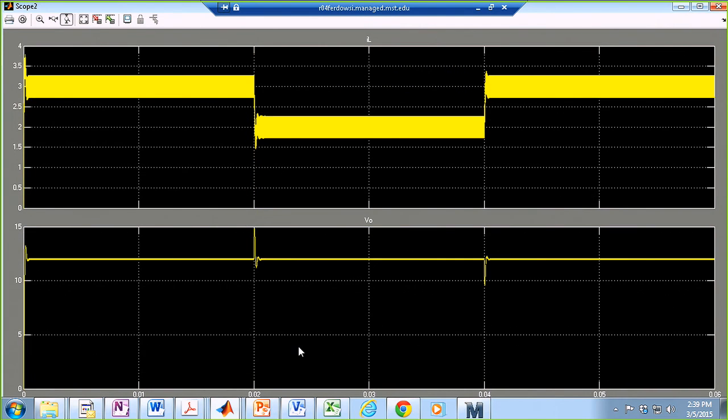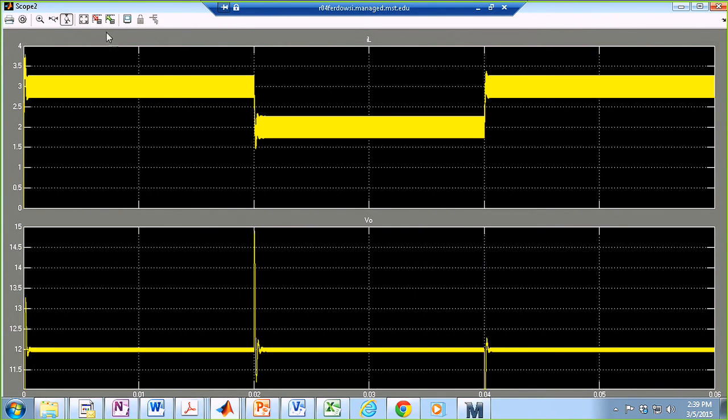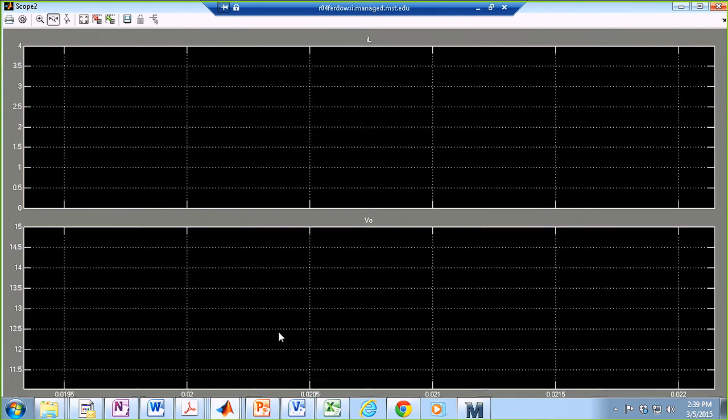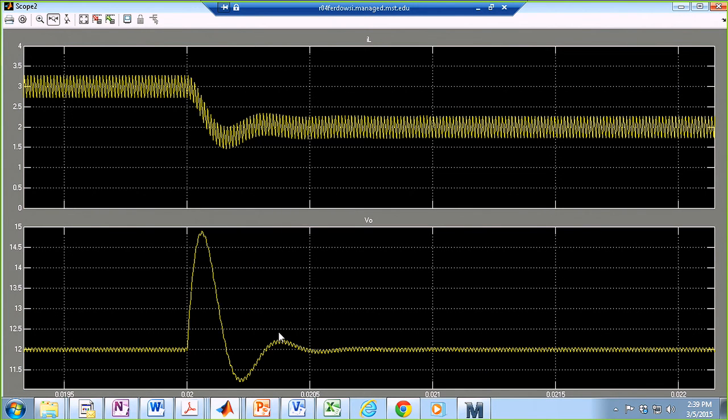All right. Technically, if our converter is ideal, we shouldn't see any changes in the output voltage, because the output voltage under steady state conditions is independent of the value of the load. But unfortunately, you see a behavior like this, for instance. So my output voltage before was 12. After the transition is over, it again goes back to 12, because under steady state conditions, load should not determine your output voltage, assuming that you're operating under continuous conduction mode.